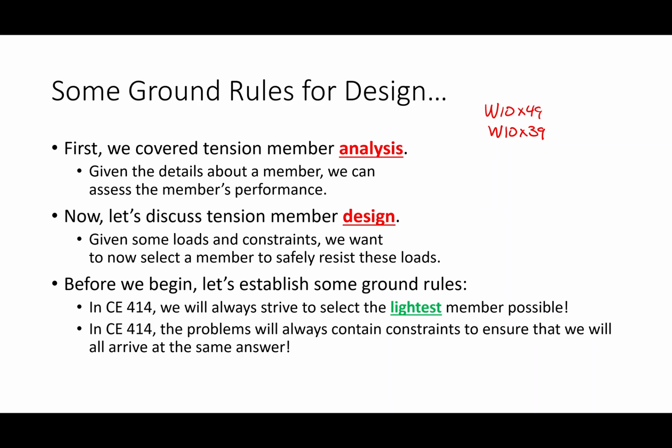And then there are also other issues, like maybe if you want the W18 by 76, there's a 12-week lead time, but if you go with the W24 by 76, you can have it in 2 weeks. You know what I mean? So there's also those issues as well. And so we're going to use the lightest member possible, but I do want to throw a little bit of a dose of the real world that you've got to be a little flexible with how things work in the real world.